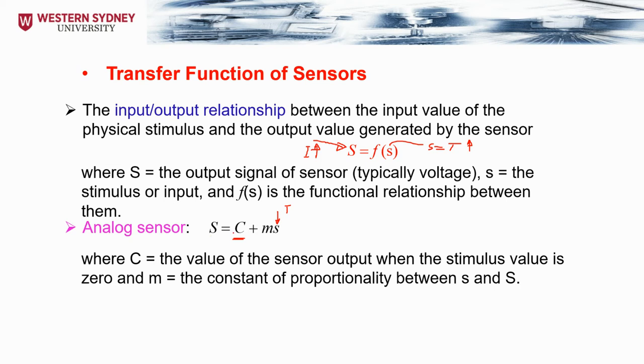Now, if this temperature is going to be dropped down, this value is going to be negative, and thus the current that is going to be measured is going to be less than the value which gives me the constant 0, and thus we're going to have the reading to be negative. If it's going to be increased, then we're going to have above the current at reading the parameter 0, and thus we're going to go for the higher reading for the sensor.